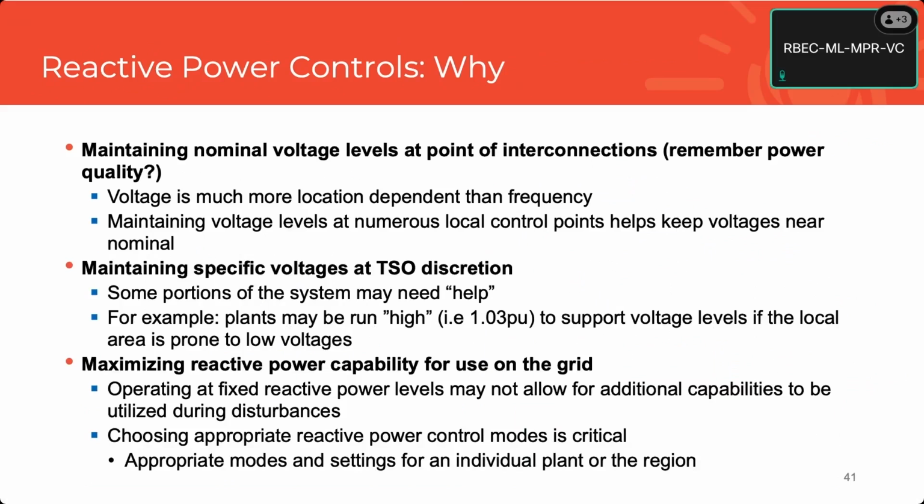All the things we talked about. If you're using a good model, even just a generic model, they have voltage slope, frequency slope, droop controllers in there with logic. It's much easier to just run one and see what it does, if it does what you expected by measuring what you expect, than it is to guess and do the math and figure out exactly where your operating points are.